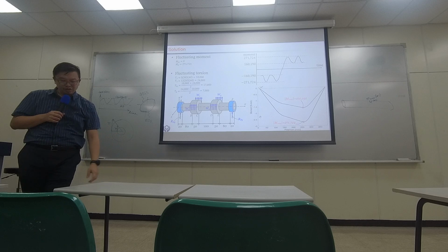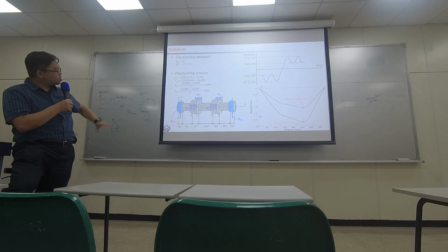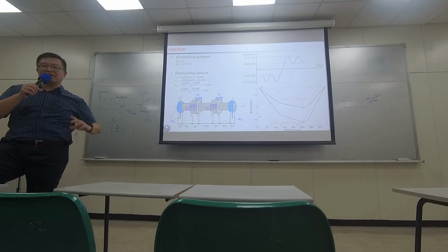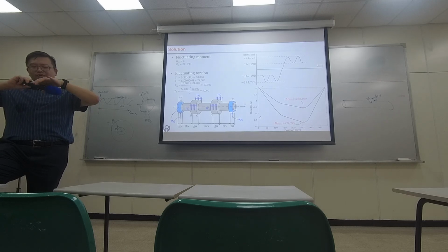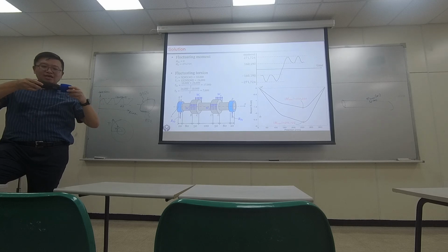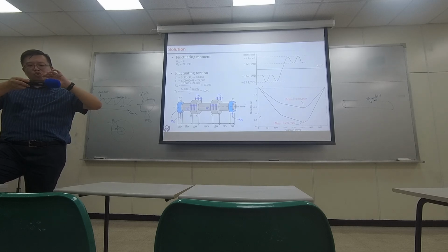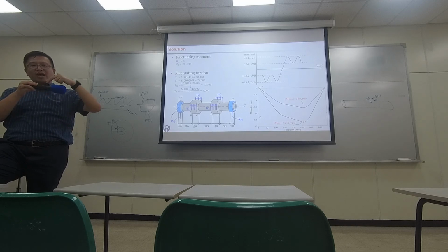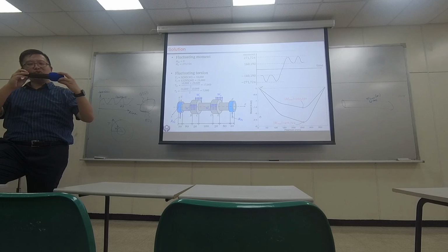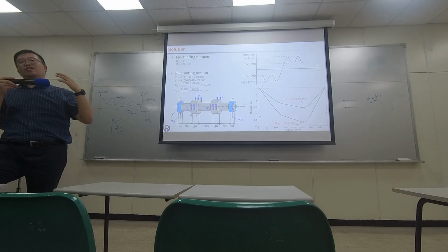For the torque portion, you realize I didn't change anything. Why is that? Because even though we are twisting the shaft fluctuatingly, sometimes tighten, sometimes loosen, we are twisting the shaft entirely the same everywhere at any position. So even when the shaft changes its angle to a different place, we still twist the whole thing the same way.